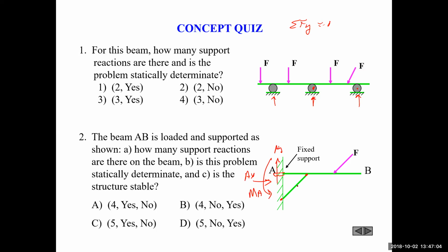But it's a 2-force member. If it's pinned on both sides, it's a 2-force member. If it's not pinned on both sides, then yeah, you would have 5 forces. But if it's pinned, the direction is going right along that beam there, and we just don't know the magnitude. So we've got 1, 2, 3, 4 unknown reactions. Is it statically determinate?